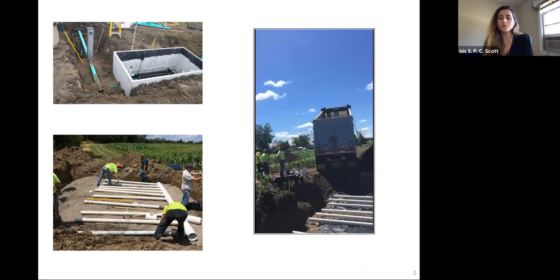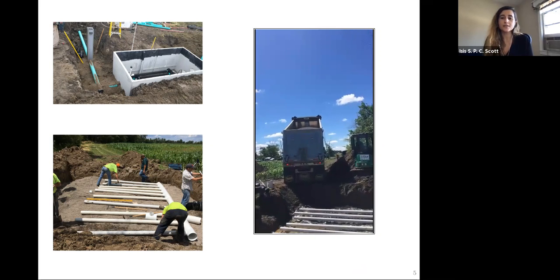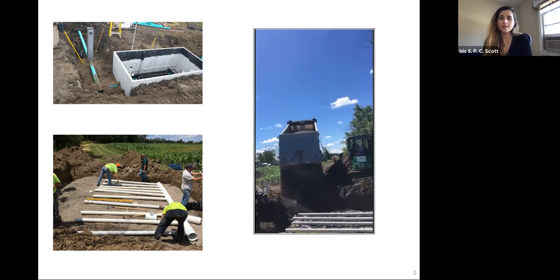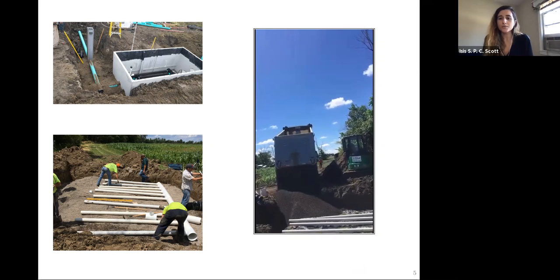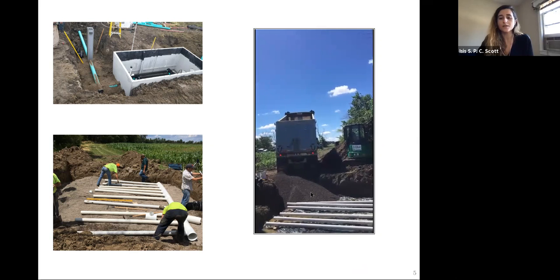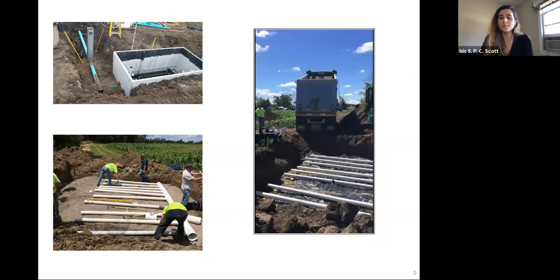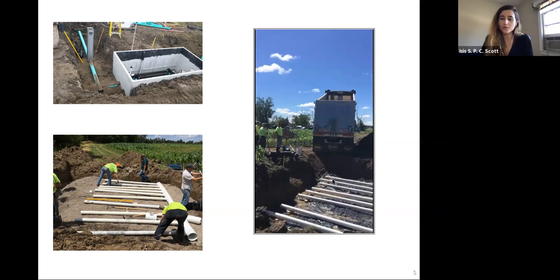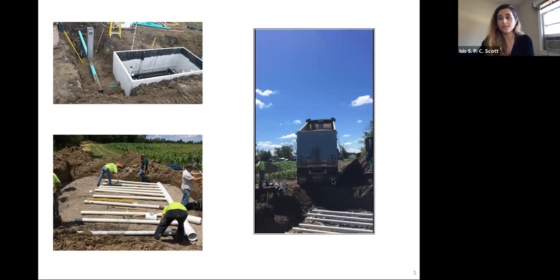The phosphorus removal structures are extremely flexible for different landscapes, for different environments, both urban and rural, and we can adapt the design of these structures according to the needs. But essentially what we have is a set of pipes on the bottom, then we come up with the PSM, and then another set of pipes will connect this structure to the tile drainage, and the bottom set of pipes will connect that structure to the closest ditch.